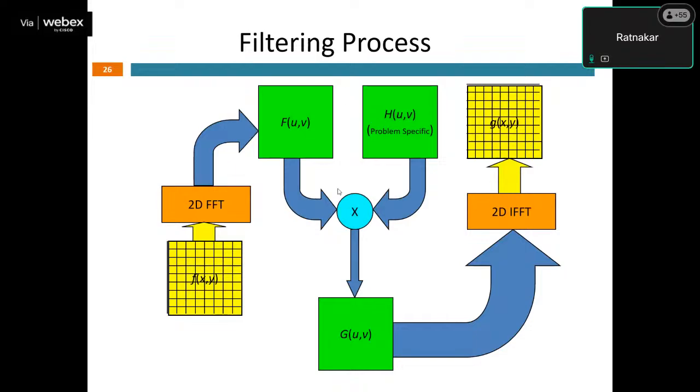We carry out this filtering process in the frequency domain, which is why it is known as frequency domain filtering. It has several advantages over the spatial domain. If we try to highlight a particular frequency band, for applications like synthetic aperture radar or remote sensing image applications, we may have to highlight some properties of the image in a different frequency band.